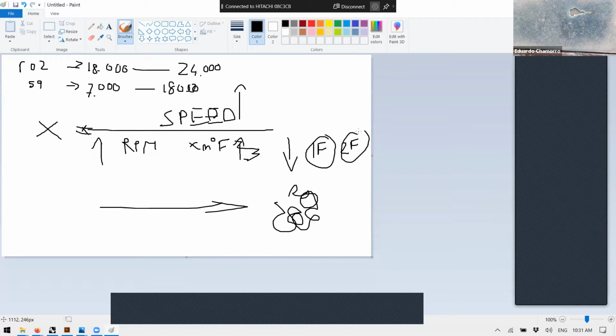It means you can accommodate a lower speed and it's not really sensitive, or you accommodate a higher speed and make the end mill work a little bit harder and it still will work well. Maybe it's overheating a little bit, yes, but it's a little bit forgiving, the 1 flute end mill. When you go to a 4 flute end mill, they become really fast and hot. Why? Because you have really small space for the chips, and that means you need to cut a lot with each one of the flutes, and have the flute space always filled.